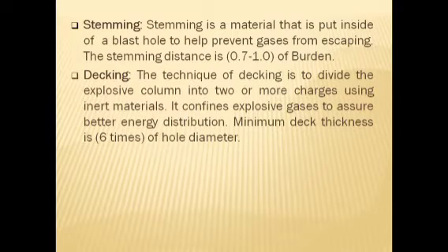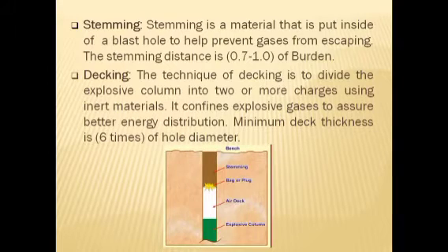Decking. The technique of decking is to divide the explosive column into two or more charges using inert materials. It confines explosive gases to assure better energy distribution. Minimum deck thickness is 6 times the hole diameter. This is the picture in which stemming, bag or plug, air deck, and explosive column are clearly shown.